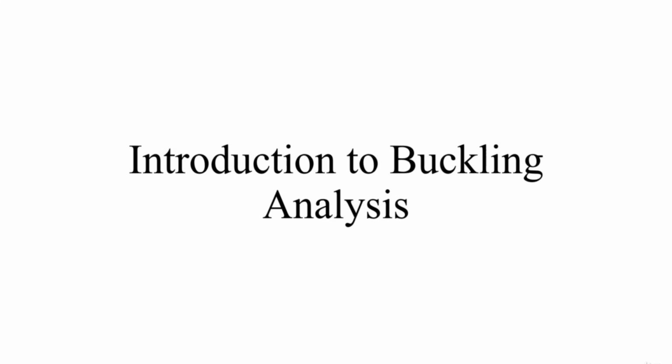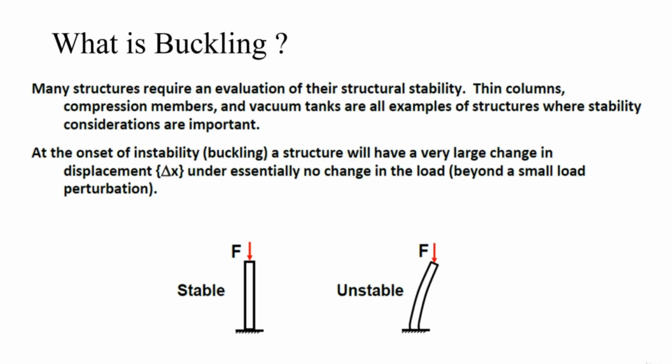I am going to introduce you to what is buckling analysis. So what is buckling? What happens if we have a long slender structure like this and I apply some compressive force over it? Even if the stresses present inside this body don't cross the yield limit of the material, this body is going to fail.